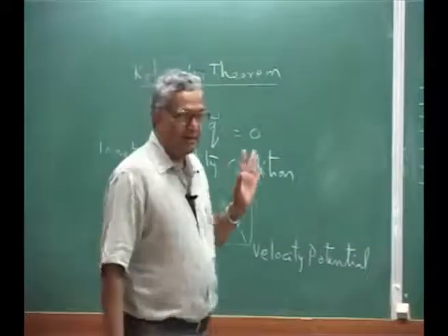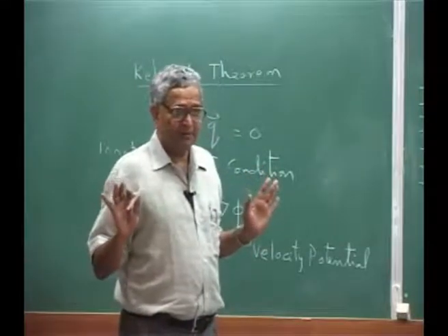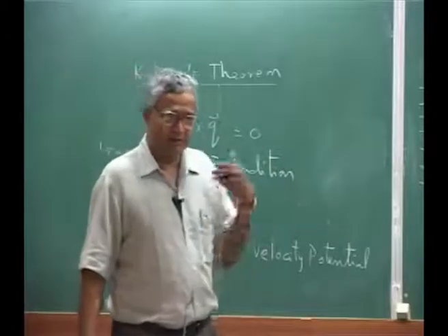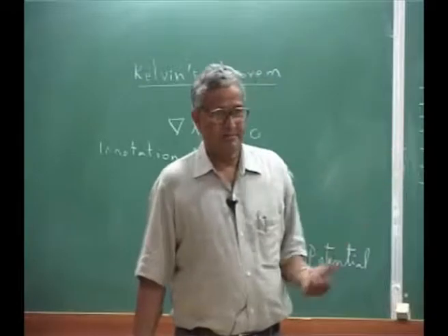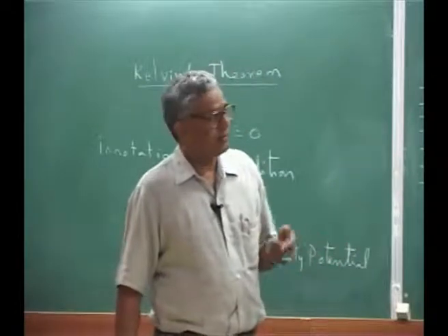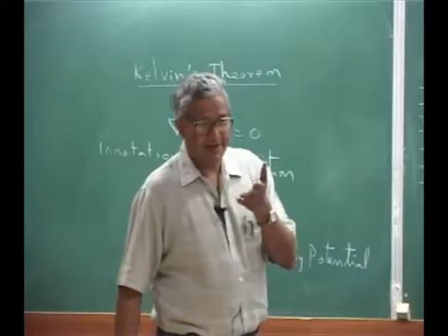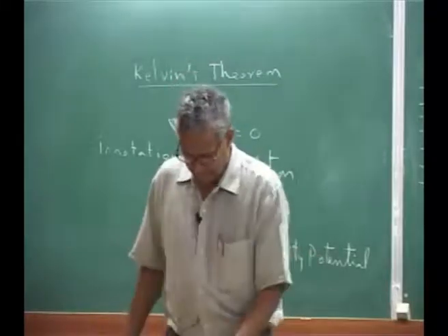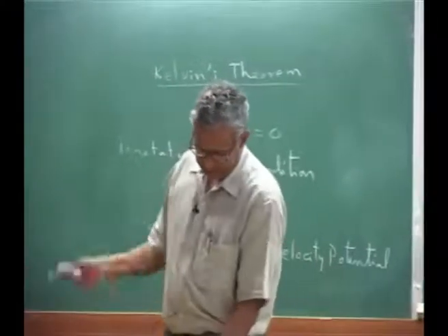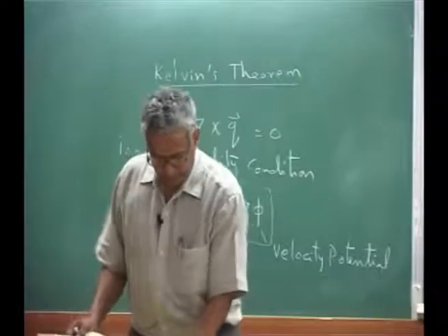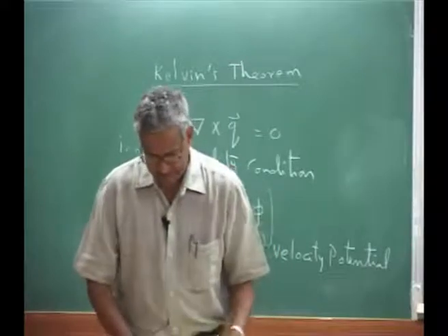This is what the whole potential theory is about. Okay. You assume a wake structure even in rotor blades. We have something called a vortex theory. And then you use prescribed wake or free wake analysis to get the effect of this. Okay. Now, let us go back to the formulation. I just want to derive a few important things.